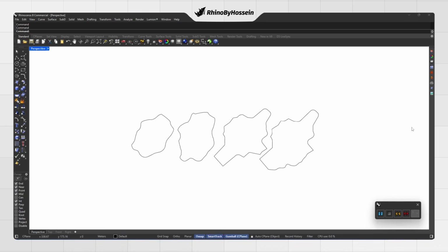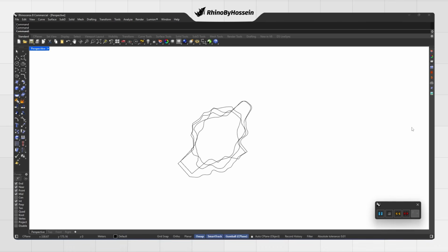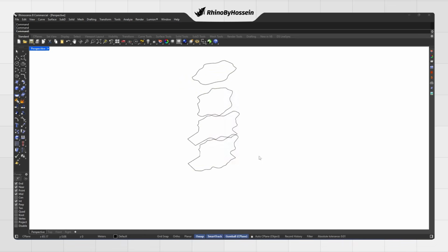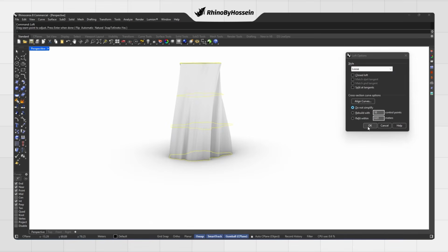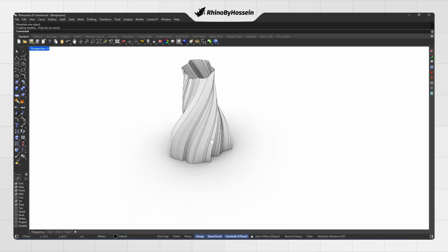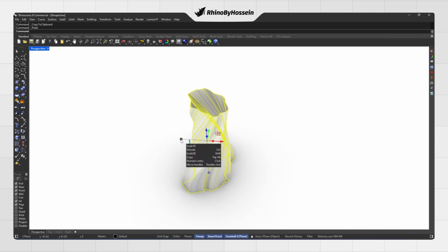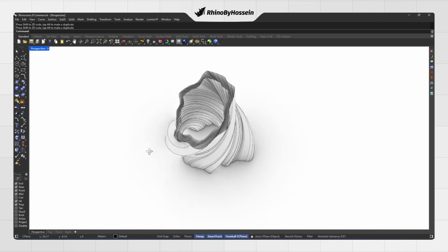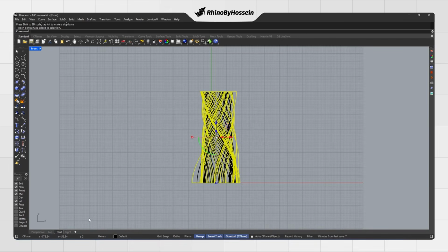I defined the profiles based on the required floor areas at different heights and placed them accordingly. Then I created an inner shell with a 2-meter offset to form the terraces. Finally, I sectioned the surface, separated the floors at 4-meter intervals, and extruded the resulting curves.